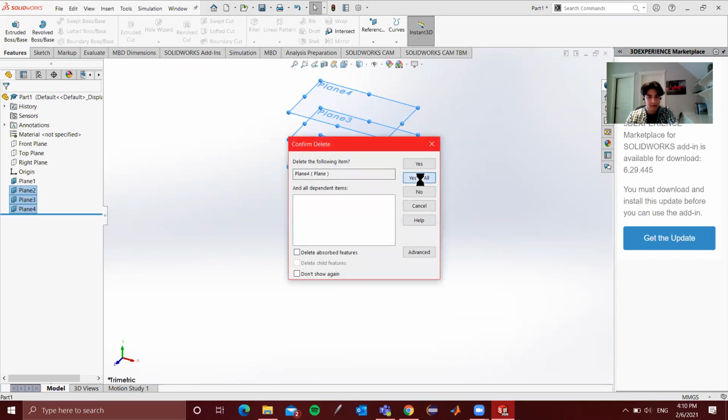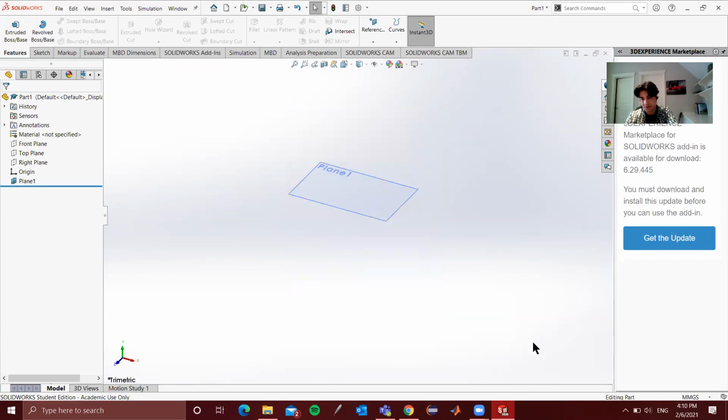As well, it doesn't really matter for the purpose of this tutorial, but I'm going to change my unit system. As you can see here, we're currently in MMGS units. As it says if you hover over, we're in millimeters, grams, seconds. Depending on the type of project you're working on, you're going to want to cycle through these. But for the purpose of this, we'll stick with CGS units. So centimeters, grams, seconds. All right.